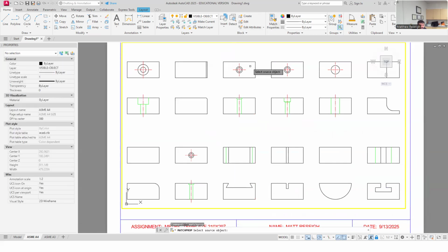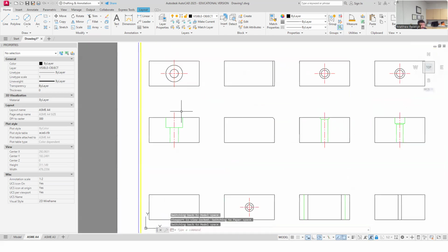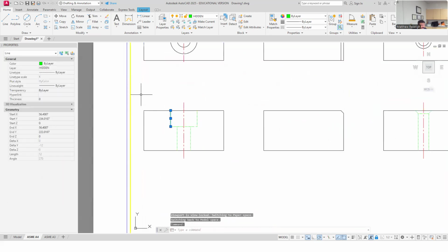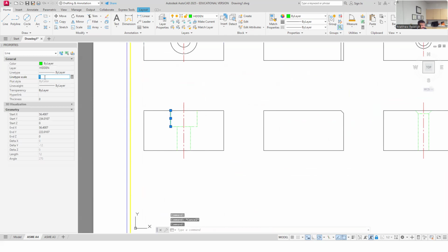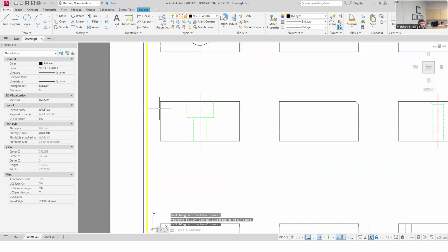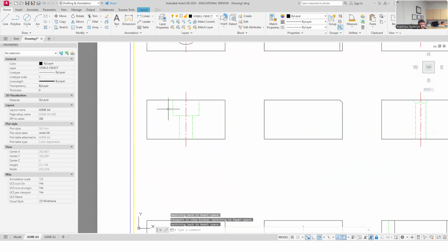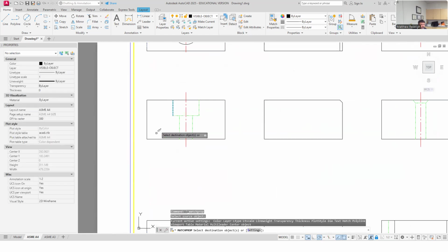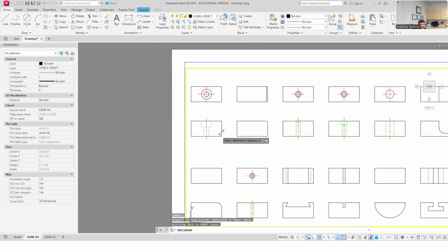And then I just have one more, maybe of the smaller circle line types. My nature of line type scales is generally, I pick one and like it or not. Like I'm going to go over here, and I didn't join any of these two. I could have joined some stuff, but it's okay. Join, maybe I'll do a 5 on these as well. You could argue that I could make that a little coarser, but I think I'll leave it as a 5. Sure. I'll match these properties. That one, you can pretty much go around to all of my hidden lines.